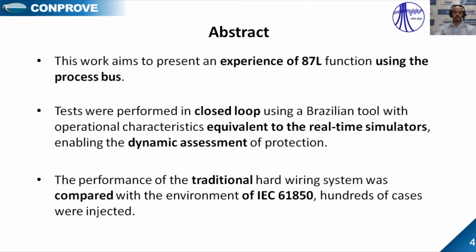And now about our work, it's an experience of 87L protection using the process bus. They were performed in a closed loop tool with operation characteristics equivalent to the real-time simulators, enabling the dynamic tests of the protection. The performance of the traditional hardwiring system was compared with the IEC 61850 environment with hundreds of cases.